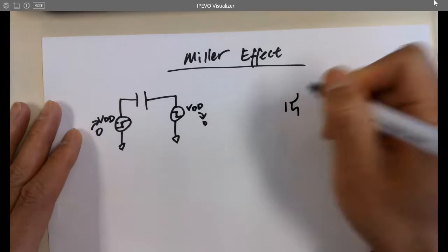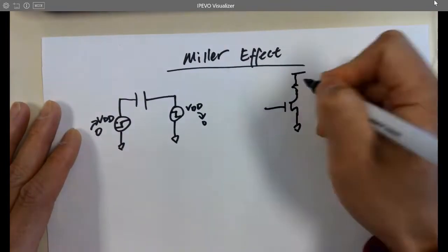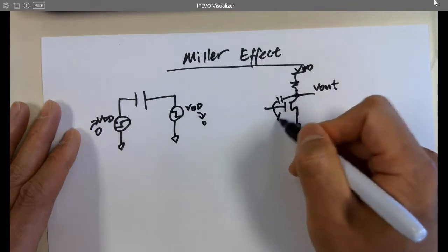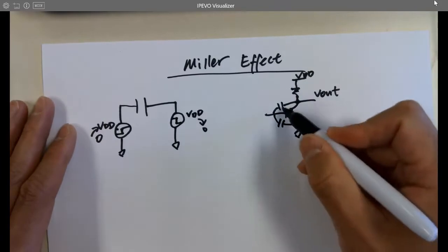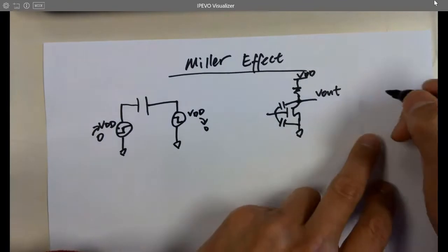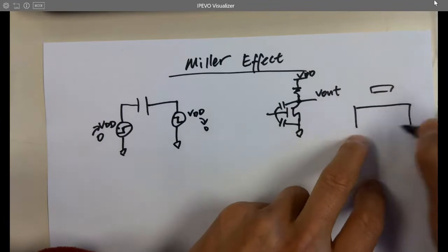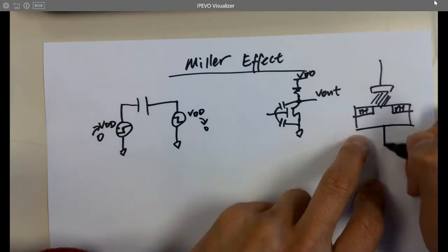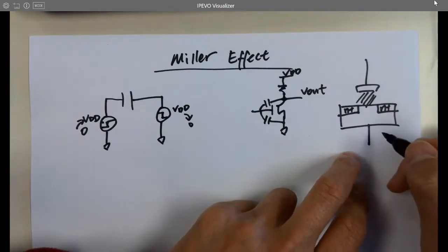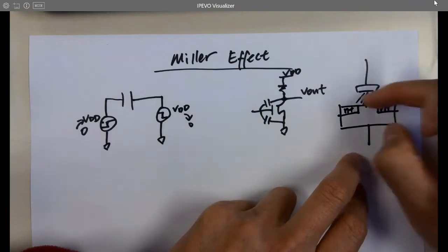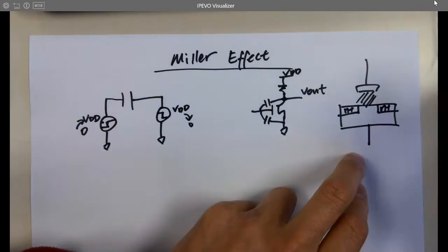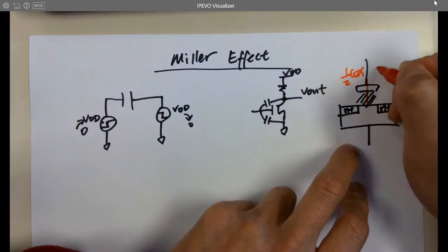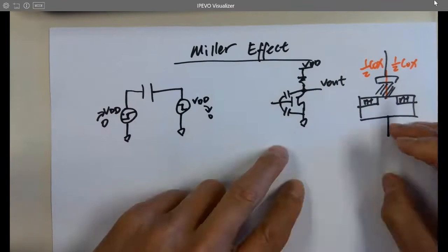Because if you look at the NMOS, VDD is here, this is a resistor, and this is a VL. I've told you that there's a parasitic capacitance here from the gate dielectric material. There's the gate, a dielectric material in the middle, and the substrate, which is connected to ground. So you can consider two metal plates with dielectric material in the middle. The textbook models this gate as two halves, each half of Cox, the capacitance of the oxide layer. So these are the two caps.